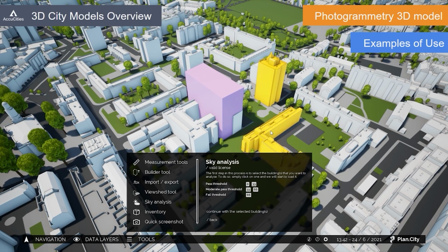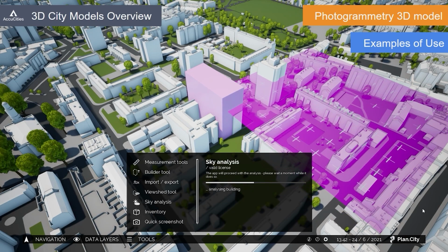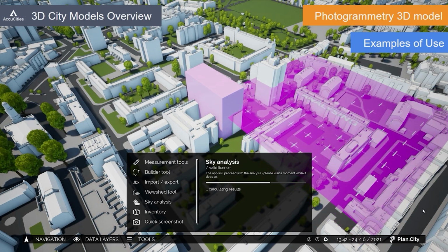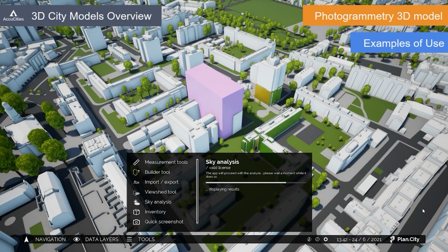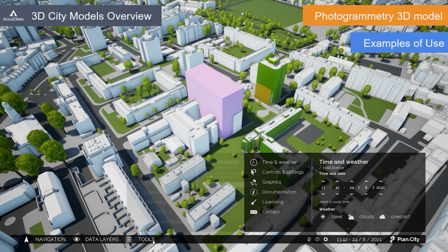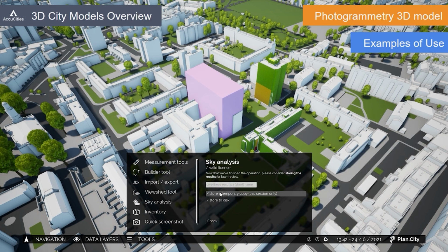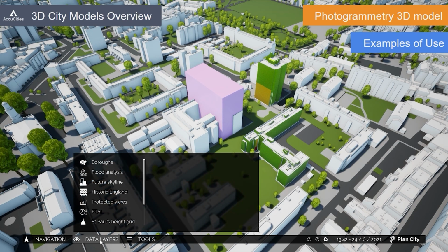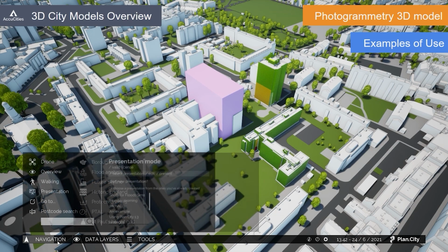Building envelope constraints stemming from local planning regulations or from acquired rights such as rights to light can have a significant impact on the building design. Visual Sky Component calculations assess the daylight impact of different massing options. This type of study is usually conducted by an architect or a planning consultant during the pre-planning phase and results in the generation of a maximum building envelope constraining the final architectural design.